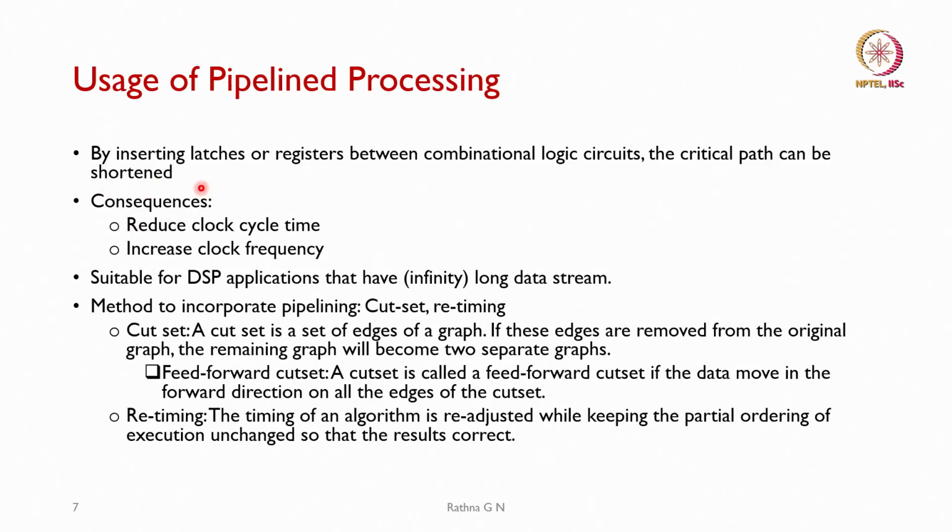The consequence of introducing this is reducing the clock cycle time and increasing the clock frequency. So, it is suitable for DSP applications that have what we call an infinitely long data stream. We are assuming that input data is coming continuously, so we have to operate on that.